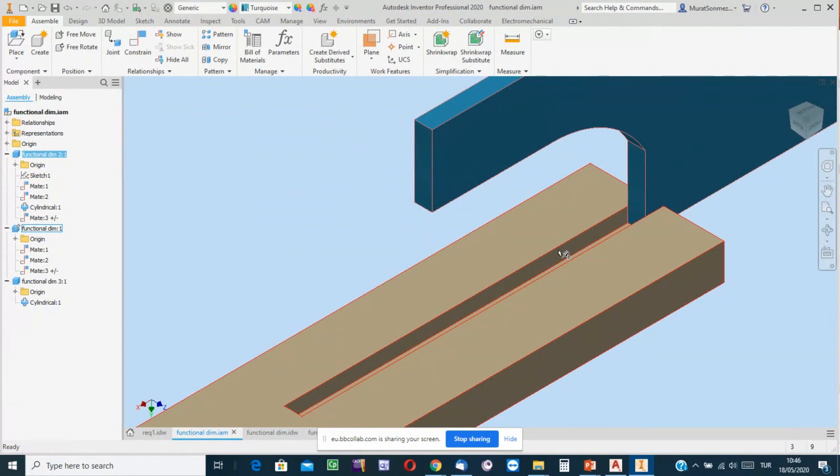Tolerance means the difference between the upper limit and the lower limit of the size of a feature. It is called tolerance. Individually, designers consider the case: the clearance between the mating features is to be in which order, a very tight connection or a very loose connection or medium order.